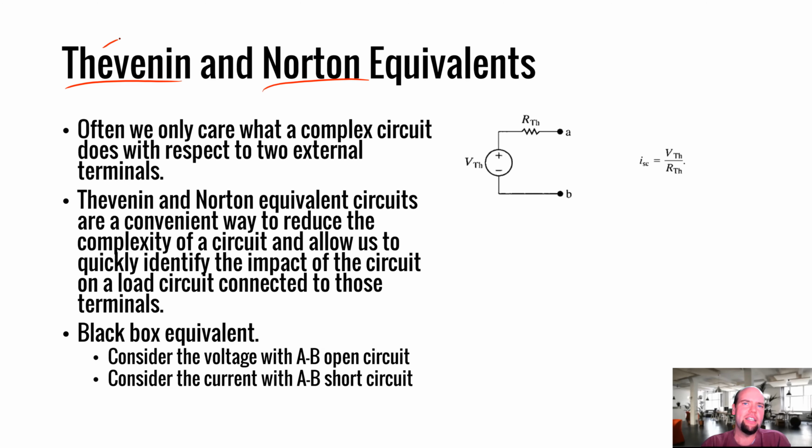So let's say your circuit is a power supply, and it's got all these unwanted resistances or non-ideal resistances, and it's got all these amplifiers that are in the process that are used to convert the current. And you're finding the equivalent of those with these dependent sources. And really, though, what you care about with this supply, let's say it's a computer power supply, is what happens when you connect a load to its terminals. You don't necessarily care about the details of what's going on inside. You want to know what happens when you connect something to it.